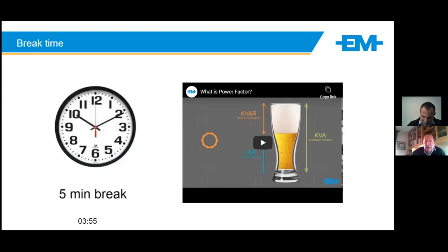Okay, so on the PFC systems, you would measure the total load, and the reactor is there to protect the capacitor bank. So it would be wired in line at that injection point. I'm not sure if that answers that question. It's very general. So maybe we can respond to him afterwards.